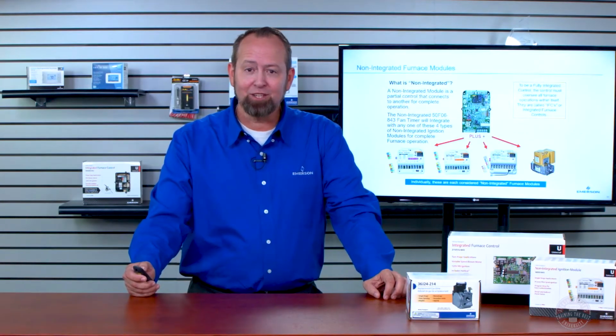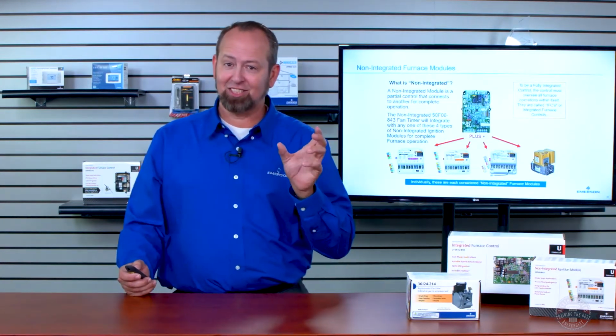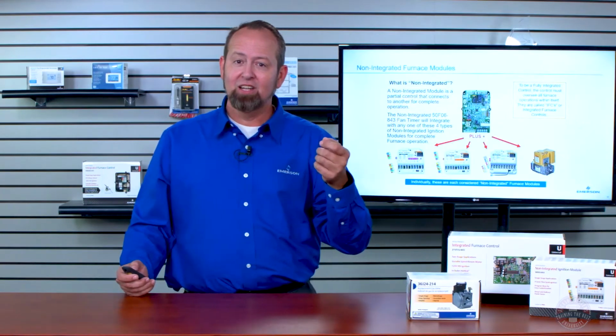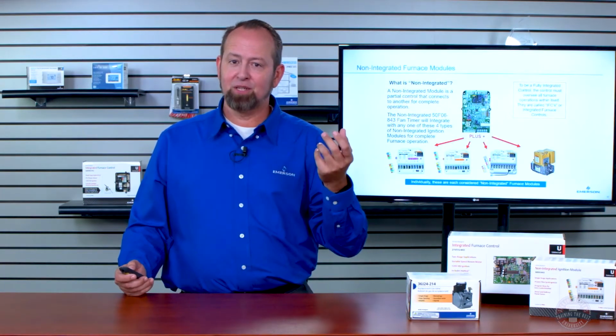Thank you for the question. Scotch-Brite is a product that was on that list. If you're using it, I would recommend that you use an alcohol wipe after it, because if you leave any foreign material of that Scotch-Brite on that rod, when it burns off, you have potential for it to build up and stay on the flame probe itself.